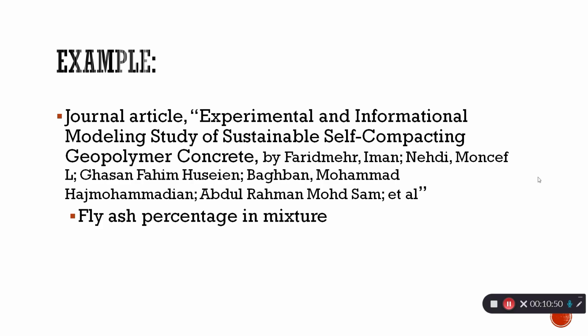The fly ash percentage in the concrete mixture is the biggest result from this study of what's important here. Results of the testing for fly ash replacement showed that fly ash is very beneficial for self-compacting concretes with binders with low fly ash levels. The workability was improved when the fly ash percentages were at 40% to 50% because of the shape of the fly ash particles. When the percentages of fly ash replacement got higher, the workability of the mixture was reduced because of the high water absorption and poor structure of the fly ash particles.